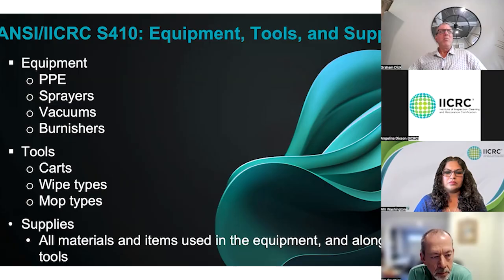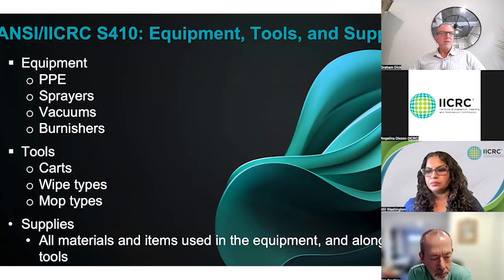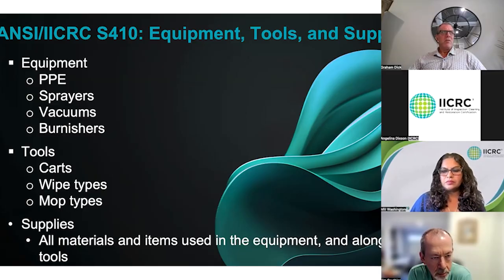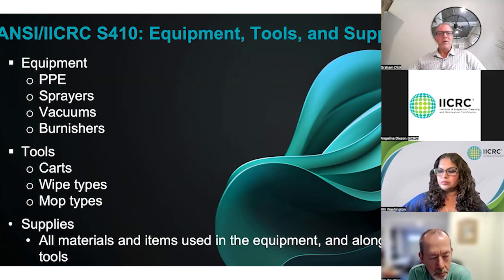Same thing with vacuuming. Vacuuming is so important. And again, is your vacuum picking up the big pieces and throwing the small pieces, the stuff that stays in the air and hangs in the air where people can breathe it, where it can create a health risk? Is that something that you've considered? And how many times I've inspected a vacuum where it was actually missing a bag or missing a filter, and certainly not being maintained to even the manufacturer's specifications.